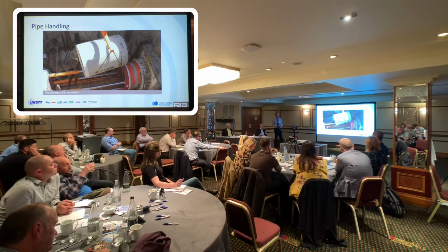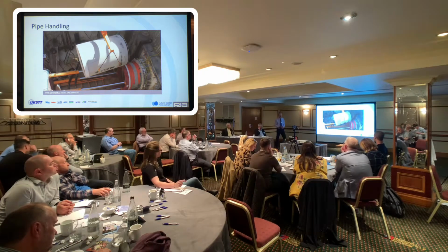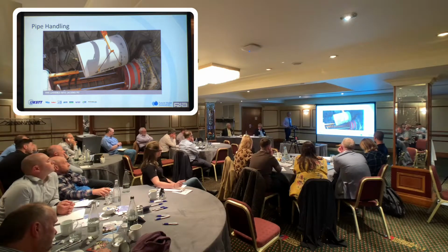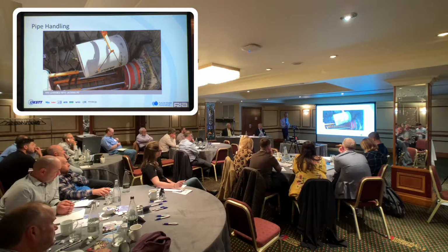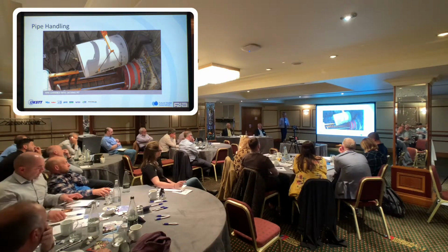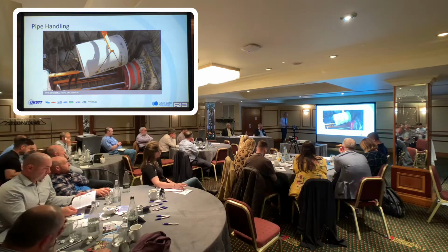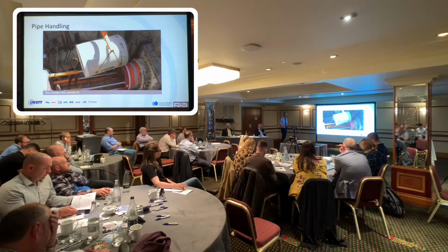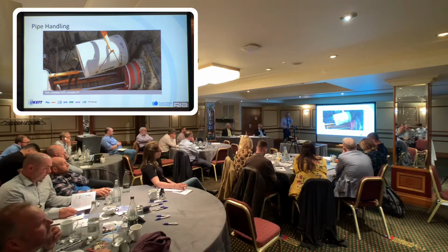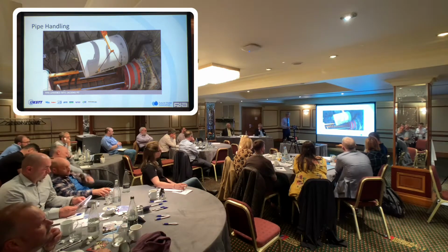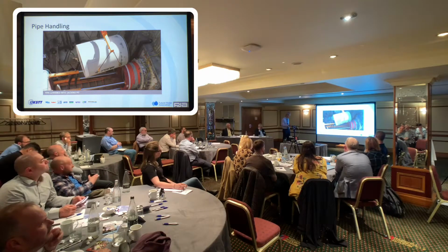So if you damage a joint, or you don't make the joint properly, and you've got leaking joints, you've got water coming down the invert, you'll get loss of lubricant into the tunnel, which causes some of the problems I mentioned earlier. You might have higher loads, you might have lubricant going into the separation plant. So handling the pipes carefully, putting the seals on very carefully, jointing the pipes carefully is an inherent part of the process, very important.